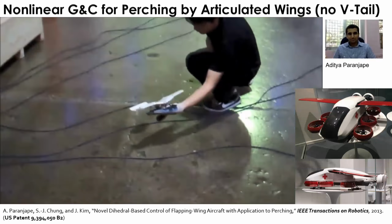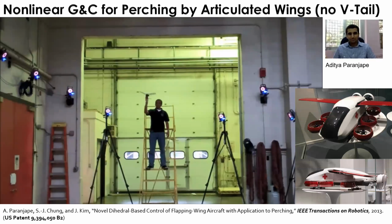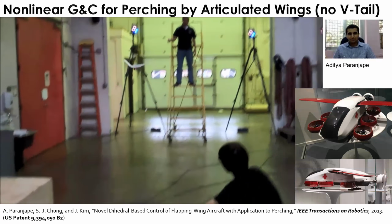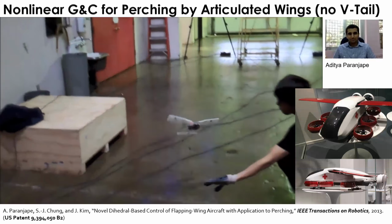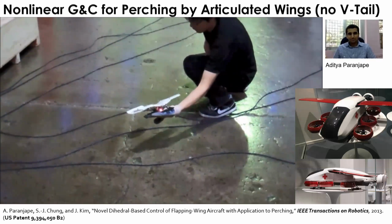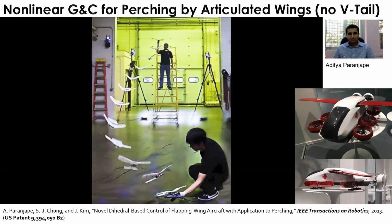We actually have a sophisticated controller using dynamic inversion, but essentially what we are demonstrating here is that you just throw a glider. Of course, we are getting help from a motion capture feedback system to get the state information, but we are demonstrating our feedback controller and motion planner so that we can steer this glider, which doesn't have a vertical tail, so it's unstable in terms of heading. But you can use the independent left wing and right wing to control the heading and steer the glider to a desired position, for example, a human hand, right? Which is an impressive maneuver for such an unstable aircraft.